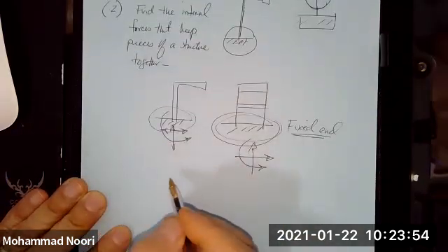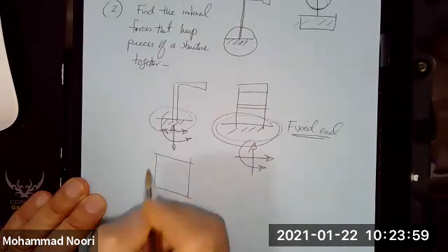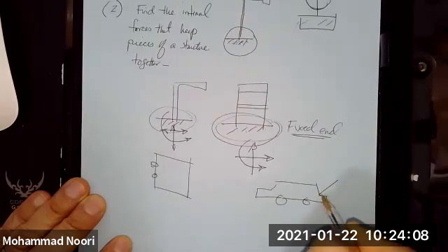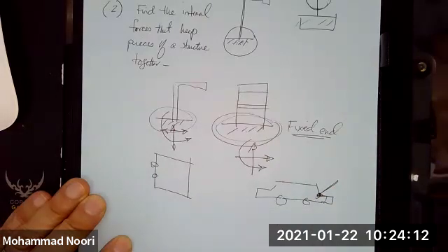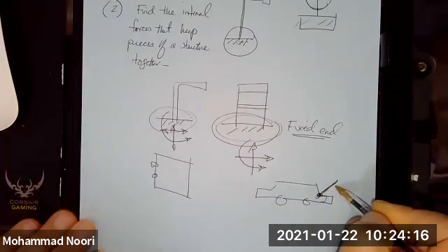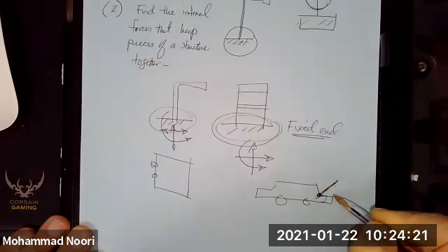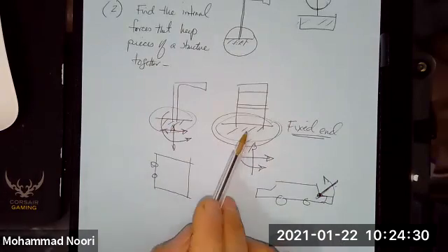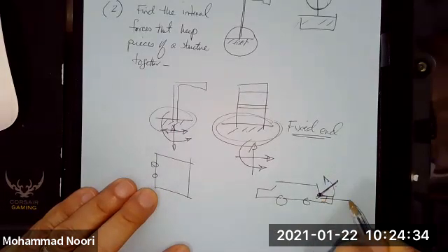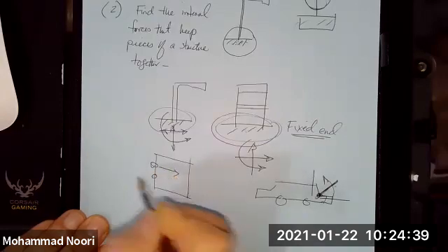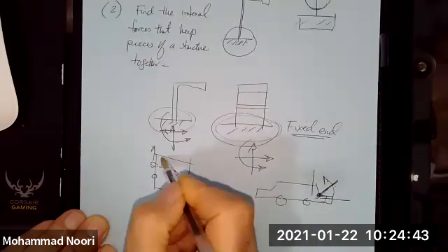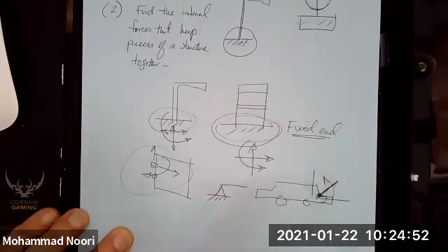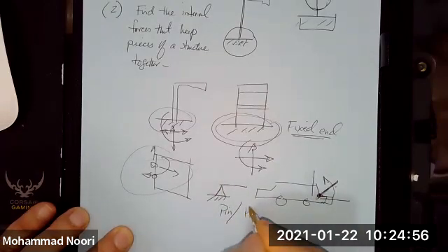The second type of support is, for instance, a door. These hinges, your beautiful car, the hood that you lift, obviously has a weight and load and so on, right? So motion is allowed in this direction, that is, rotation is allowed. There is nothing to prevent that rotation, in contrast to the fixed support. However, you cannot move a door in this direction or in this direction, right? But you can rotate the door in this direction. This type of support, which we represent by this symbol, we call a pin or a hinge.